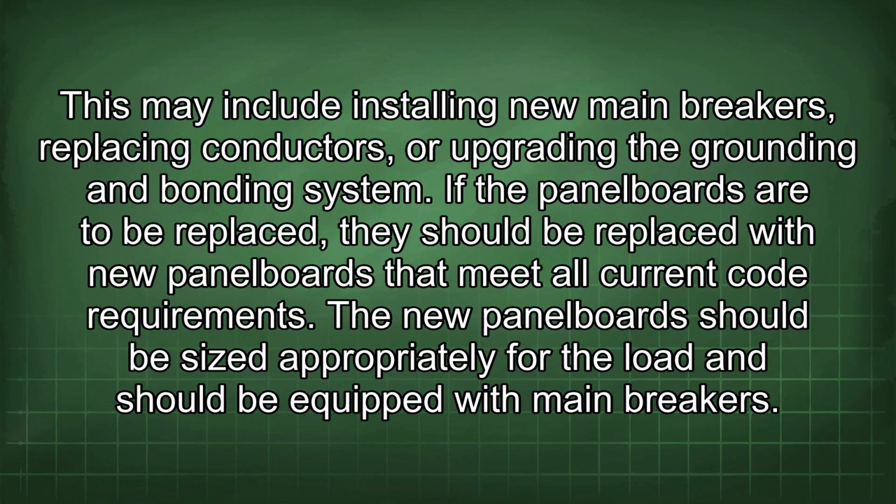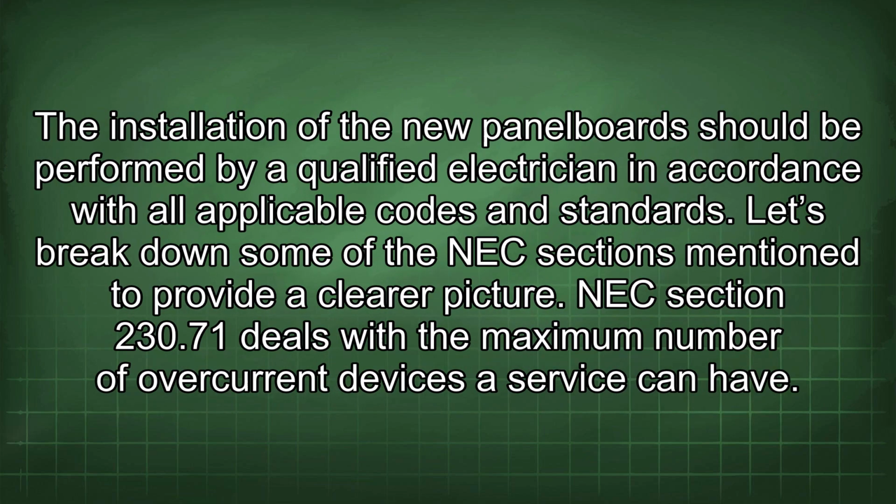If the panel boards are to be replaced, they should be replaced with new panel boards that meet all current code requirements. The new panel board should be sized appropriately for the load and should be equipped with main breakers. The installation of the new panel board should be performed by a qualified electrician in accordance with all applicable codes and standards. Let's break down some of the NEC sections mentioned to provide a clearer picture.